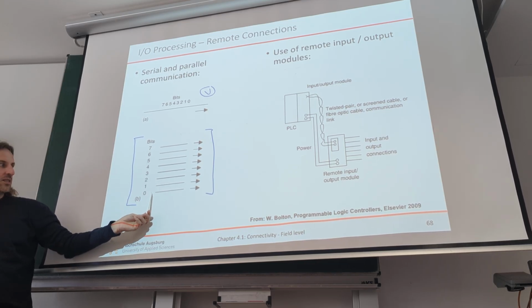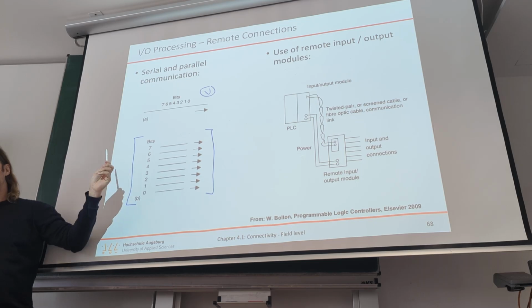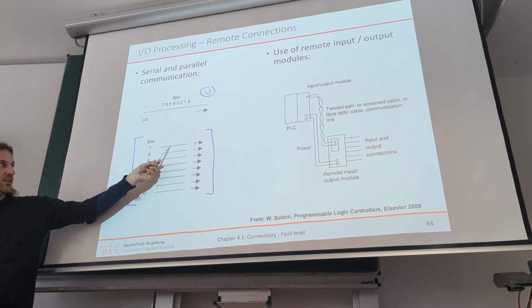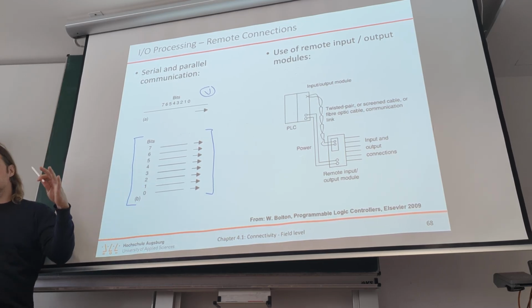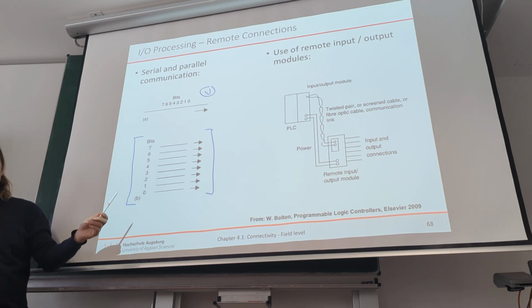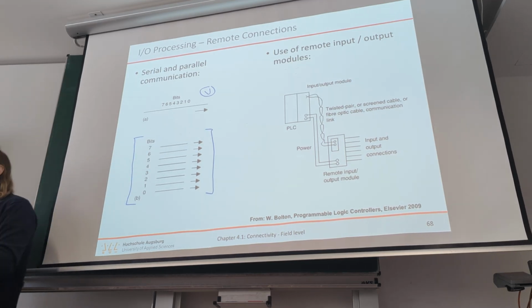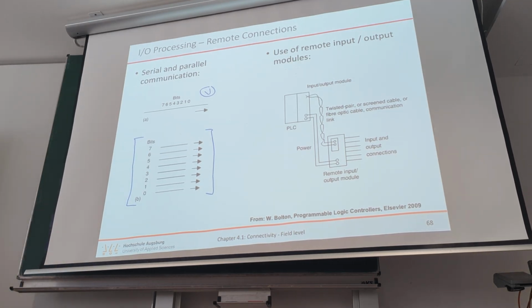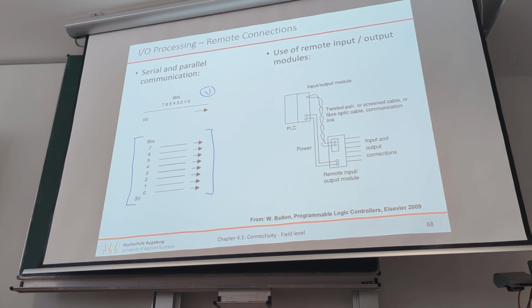And the next thing is if we communicate at high frequencies over lines and they have different length, then you get a shift in the signal, and that's not good as well. So that's why, because we can shape the signals and understand the signal in a way that we can create single serial communications, we actually use that more and more.